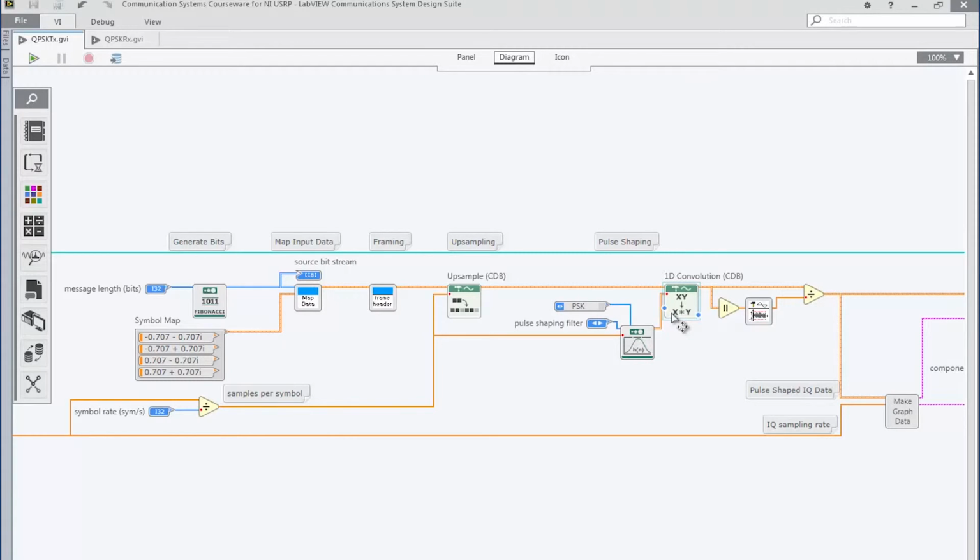An important and often overlooked step in the real world is to maximize the signal-to-noise ratio. One way to do this is to utilize the full scale of the digital to analog converter. So in software, we normalize the signal to plus and minus 1.